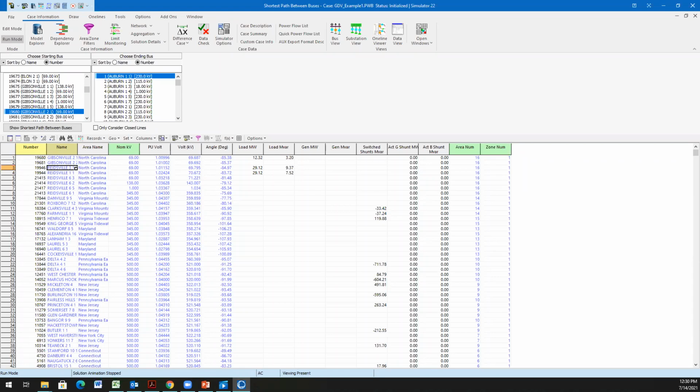So whatever object you have on there to represent the PMU, maybe a bus object or a substation object where the PMU data is being represented, just have that object use a conditional zoom so that it only shows up at zoom levels greater than X%, maybe 5% or 10% or whatever makes sense.